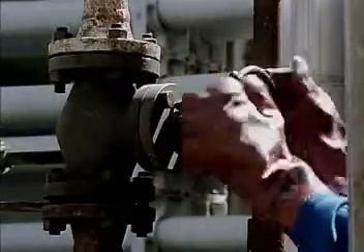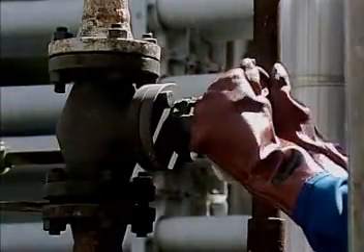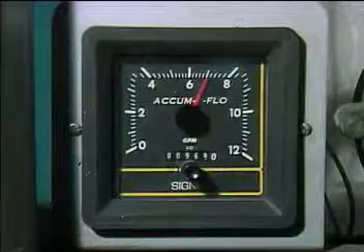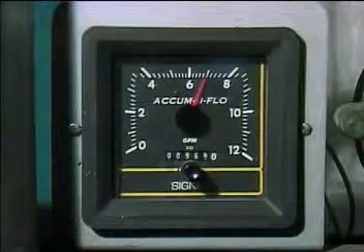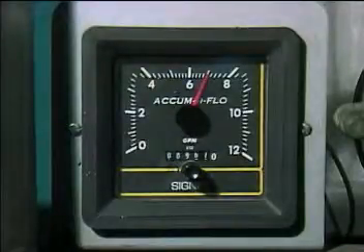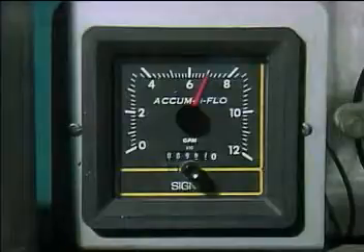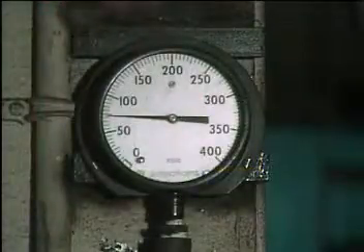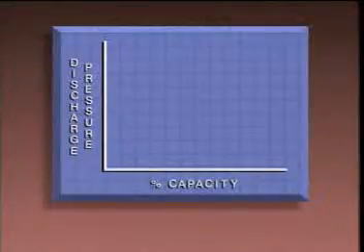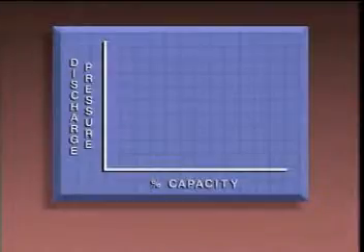Adjusting control valve settings is a common way to control the flow rate in a system equipped with centrifugal pumps. But besides changing flow, these adjustments may also affect other variables in the system. Adjusting control valve settings to change flow will also affect pressure, since flow and pressure are so closely related. The way that the discharge pressure of a pump varies with flow can be illustrated using this graph.